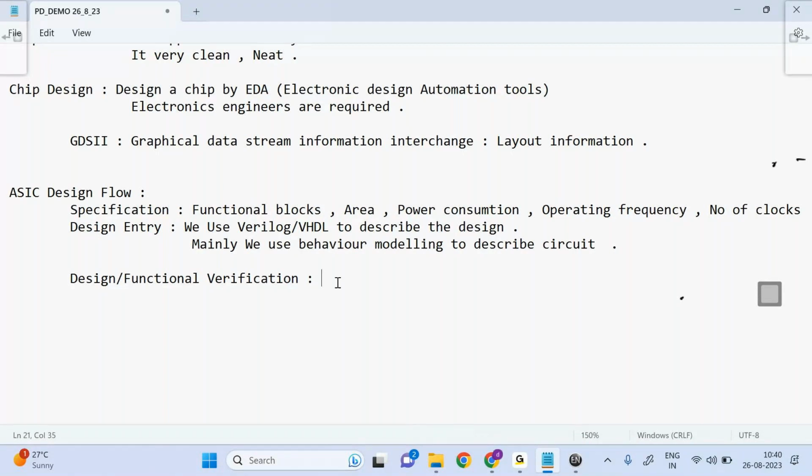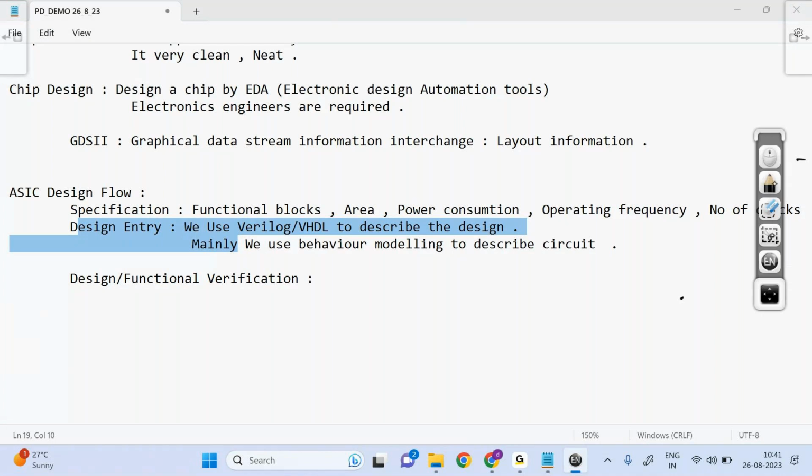You are going to form the test benches because of the design you have written. Whether this design is doing the proper operation or not, whether it has proper functionality or not, we have to test that. For example, I have written a Verilog program for a mux. The simple operation I'll take. How will I test it? I'll apply different test cases. Test cases means different inputs. I'll apply input for I0, I'll apply input for I1, and I'll apply input for the S select line, and I'll verify what the output is.